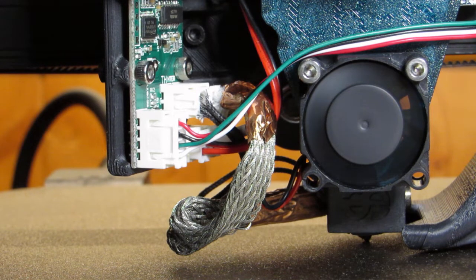I'd rather have the light off than have the light on, but I've come down now by 0.03 points. So I'm at least 0.01 off, even if 8 should have been 7. I'm still, let's say, 0.02 or 0.03 off where I was before. I'm interpreting that as Z offset has changed since last time I measured it.